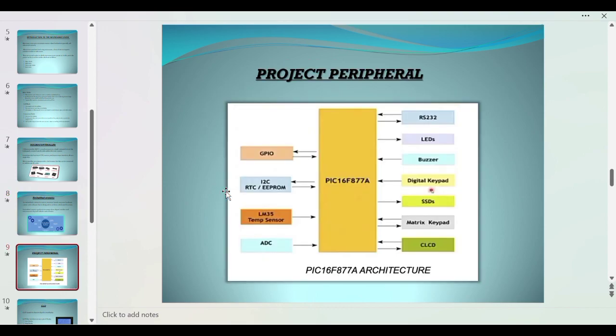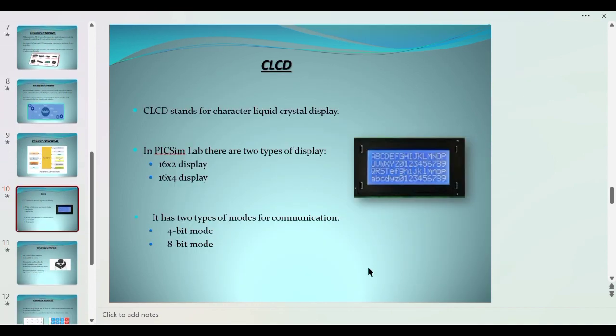Here is the project peripheral. This is the PIC16F877A architecture. Moving on to the CLCD. CLCD stands for Character Liquid Crystal Display. In PICSimLab, there are two types of display, 16x2 display and 16x4 display. It has two modes for communication, 4-bit mode and 8-bit mode.